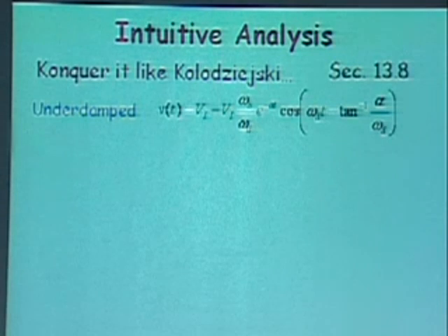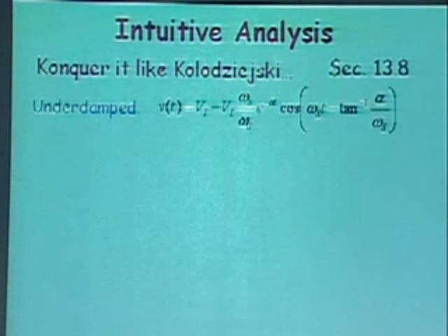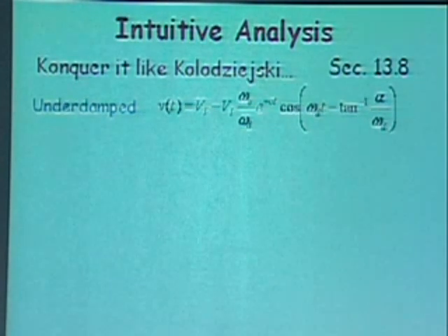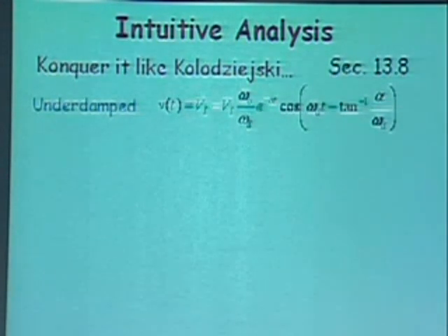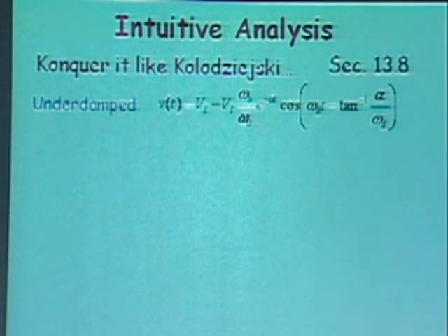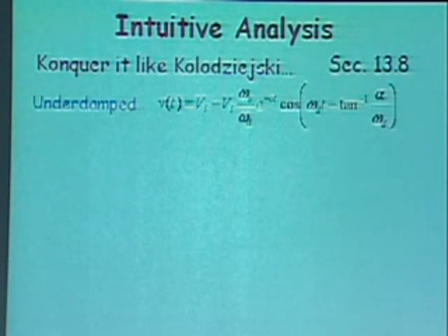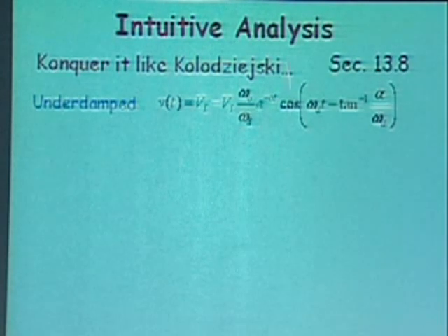To practice, you can go to WebSim and try out various combinations of inputs and initial conditions and sketch it. Time yourself, give yourself 30 seconds or a minute if you like, and sketch it and check it against the WebSim response. If it doesn't match, either you're wrong or there's a bug in WebSim. The response for the critically damped and overdamped case was very easy to sketch out. You started with an initial condition, you settled at VI, and you kind of drew it like that. The interesting case is the underdamped case, and that's what I'm going to dwell on.